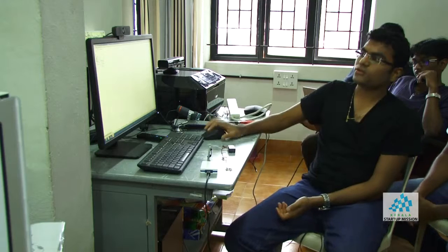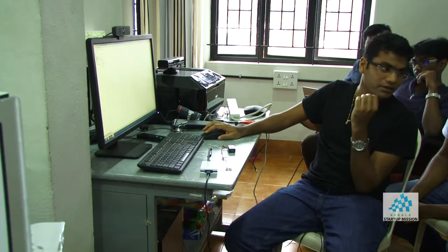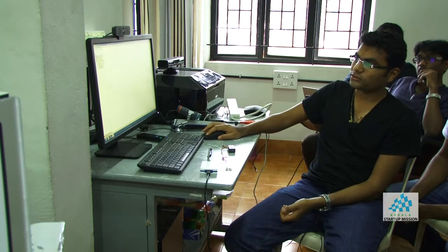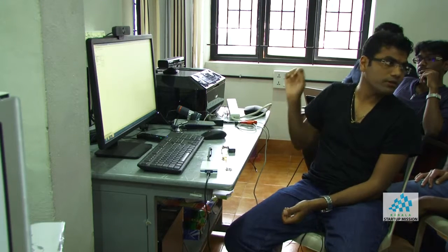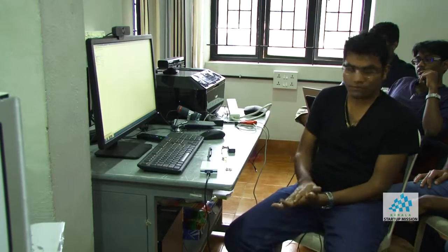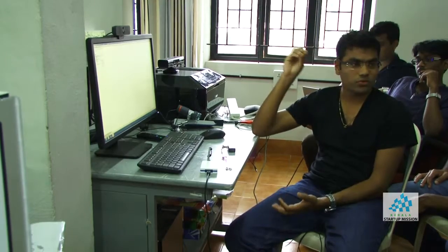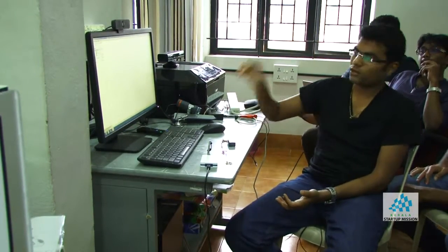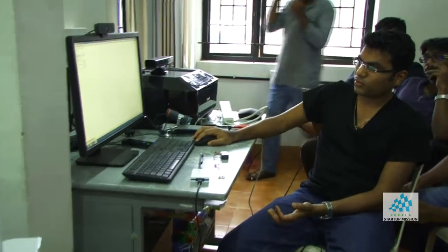Once you are doing it, you can see there is a dot there. If it's gray, it means it's not in use. So you right click and select use all, and then the dot will become green. Now you are using the library. So now we have the library for all the components we have in the Fab Lab. We can just go to this library, use the component, and make sure that we have it in our inventory.